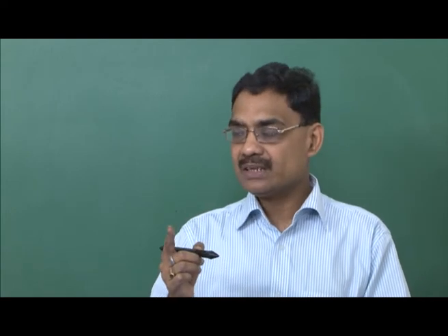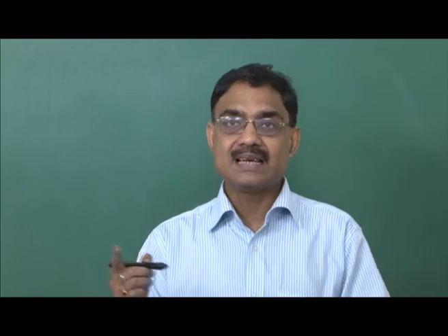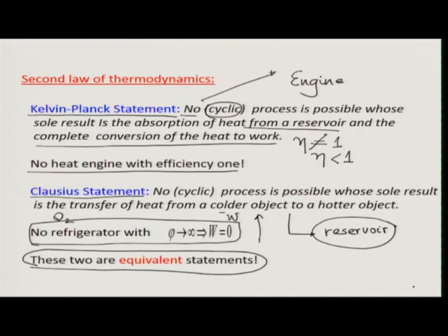So, a reversible engine will always have efficiency less than 1. This tells me the statement of the second law of thermodynamics in Kelvin-Planck form. You can similarly run the Carnot engine in refrigerator form and reach a similar conclusion. It stems from the fact that you cannot reach absolute 0, and then you cannot have an engine whose efficiency is 1. You cannot have a refrigerator whose coefficient of performance is infinity.